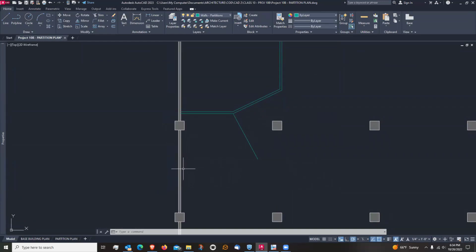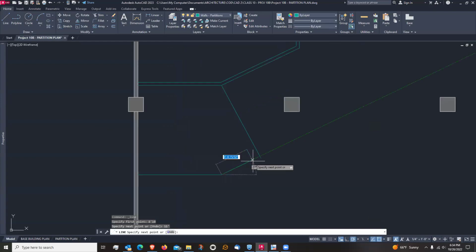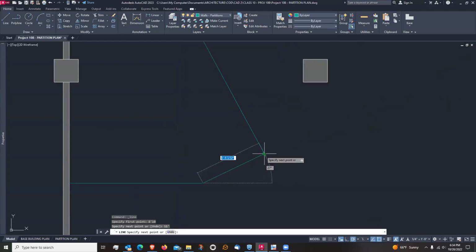this wall here is 8'10" from this column. So again, here I can use O tracking. So I'll come down 8'10". I'll go straight across 11 feet, right? Yeah, 11 feet. And then I will go up on that weird angle and I'll just go perpendicular to there.